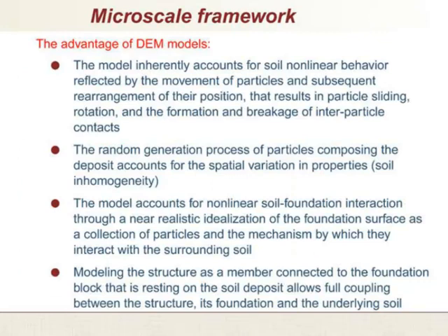The advantage of doing that is that the model inherently accounts for soil nonlinear behavior reflected by the movement of particles. So as you probably have noticed from the previous presentation, really nonlinear behavior here comes from the rearrangement of particle position and the sliding of particles, as well as rotation. That is the main source of nonlinearity using these DEM techniques. So there is no need for any additional parameters as in continuum models to do the same job.